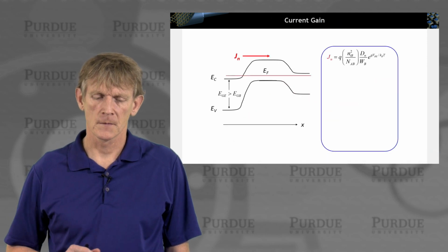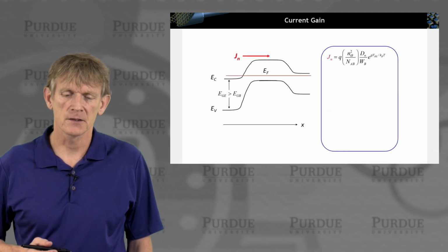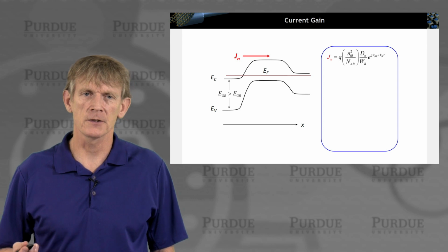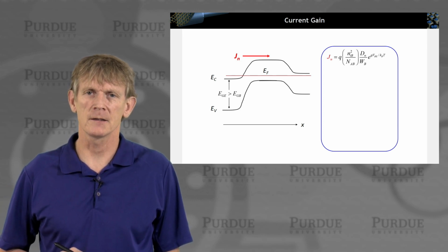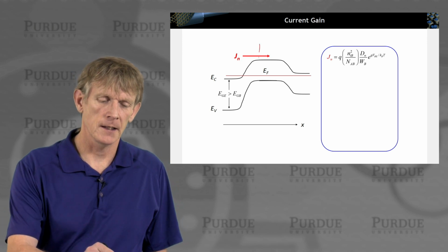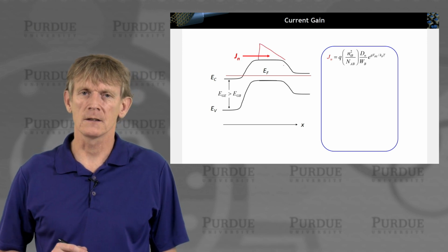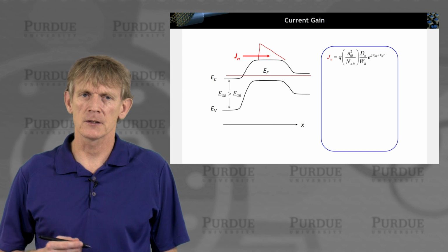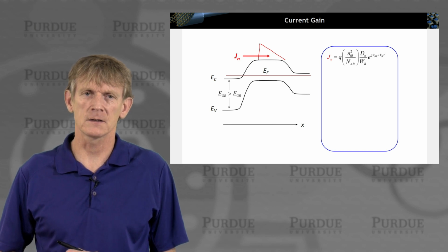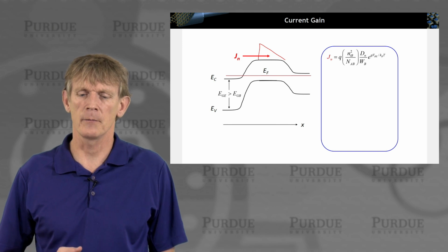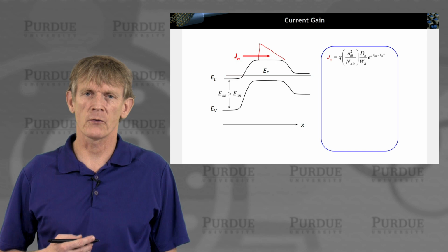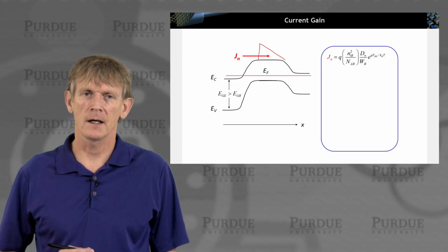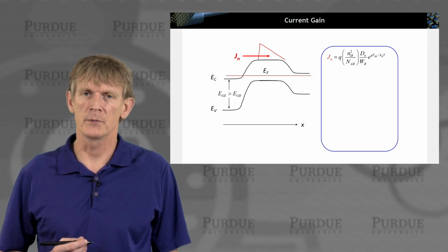All right. So let's write down the expressions. We don't have a heterojunction. We can use the normal drift diffusion expressions we've had before. Again, everything works the same. We can write down a differential equation for the electrons and see that they're linear dropping. We know how to calculate the boundary conditions. All of that stuff just transfers directly as if we had the normal BJT.